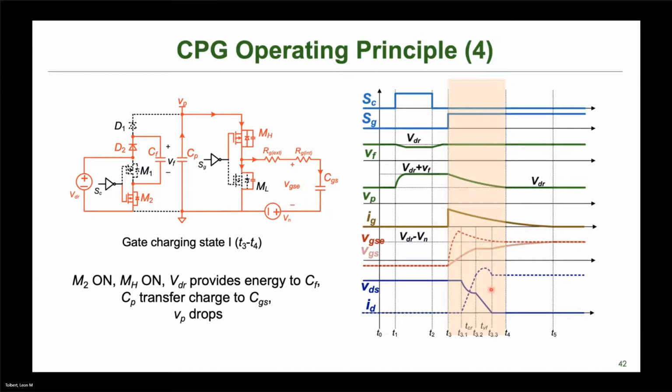Now let's take a look over here at our waveforms. Again, you can see that the voltage that we've applied to our device here is quite a bit higher than a typical gate drive voltage. But yet this voltage that we see internally, VGS, it's not.